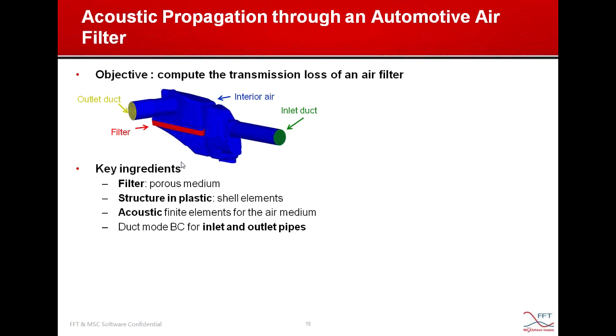In this air filter, we first have the structure of the filter made of plastic, and we use shell elements to model that. The interior air is modeled with the finite element method, and the filter itself is modeled with porous material.